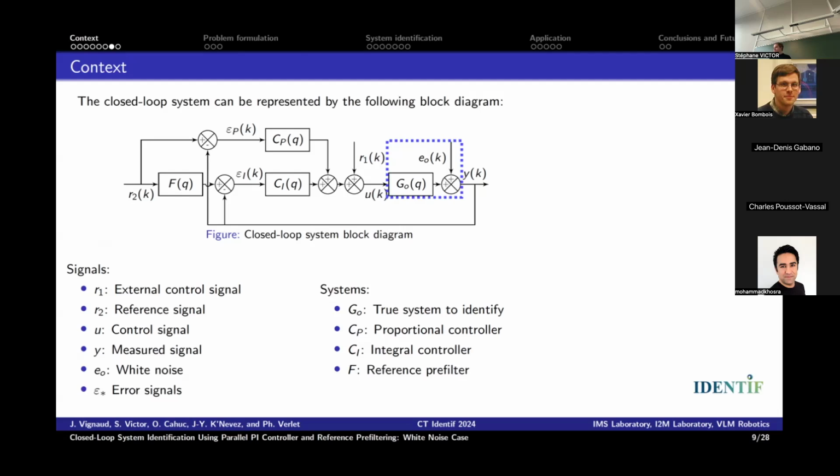Yeah, but if there is colored noise, then you can use Box-Jenkins, and that will be the best method. Well, the IV method will always work, but if you don't use optimal IV, then you'll have a variance which is higher than with Box-Jenkins. So on top of that, I think the initialization might be IV. You use, yeah.